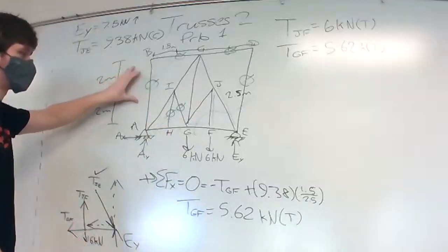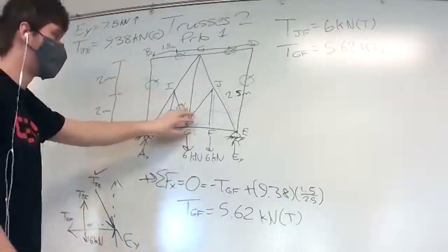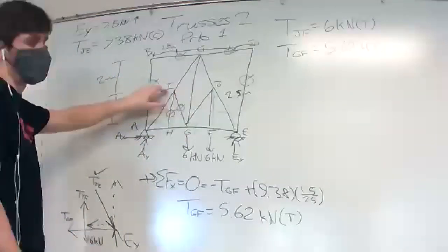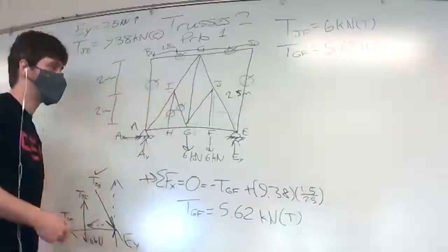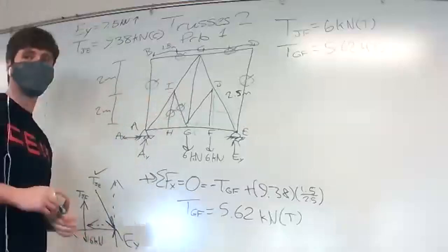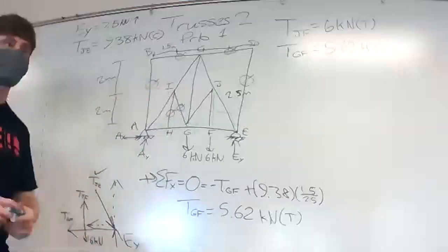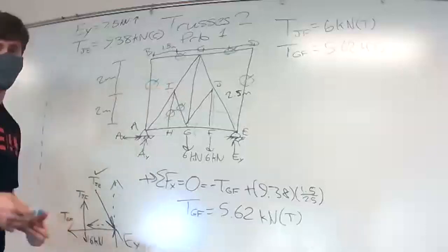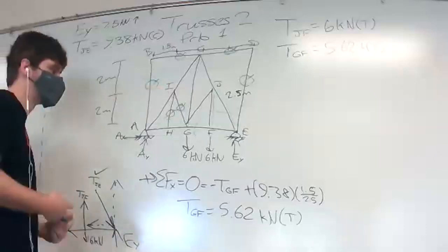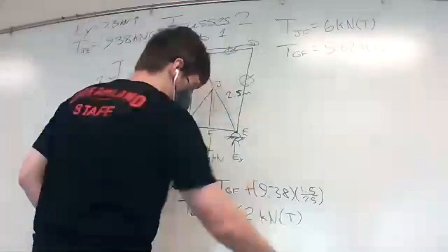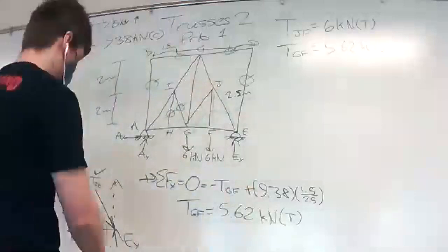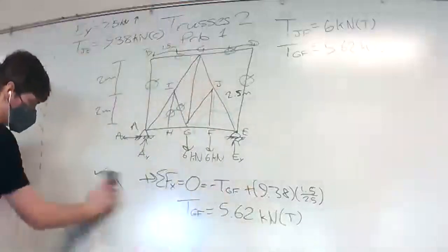So because the other side of this has nothing, this is still 0 force. And so even though there's a bunch of stuff going on at G, IG is still 0 force because there's nothing at I. So checking both sides, for the simpler side, yes, the simpler side will usually show you that it's 0. If it is 0, it's going to be 0 at the simple side. So that's where that comes from.